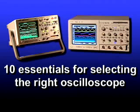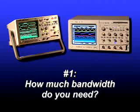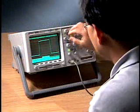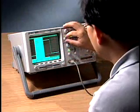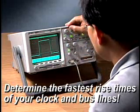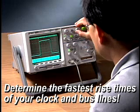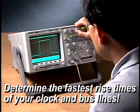in digital oscilloscope comparisons. The first step in selecting the right oscilloscope is to match the scope bandwidth to your particular application. There's more to scope bandwidth than just the bandwidth of the analog amplifiers alone. To ensure that your new scope has enough bandwidth for your application, you need to consider the bandwidths of the signals you'll be viewing. Begin by determining the fastest rise time of all system signals to be observed. It's the rise time of those critical clock and bus lines that generate high-frequency harmonics many times faster than you expect from simply considering the signal's frequency.